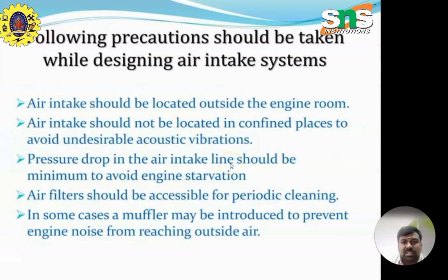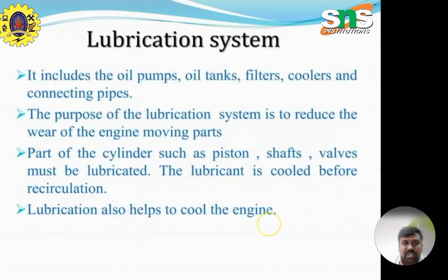The following precautions should be taken while designing the air intake systems. The air intake should be located outside the engine room. It should not be located in confined places, to avoid undesirable acoustic vibrations. Pressure drop in the air intake line should be minimum to avoid engine starvation. The air filters should be accessible for periodic cleaning. In some cases, a muffler may be introduced to prevent the engine noise from reaching the outside air.